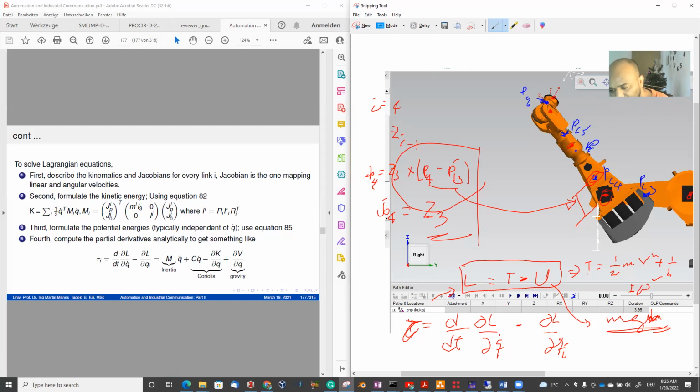If you don't know your exact point, you could use a jogging manipulator or a teach pendant on the robot, move the robot to this place, and by trial and error you will get your values. Or if you know the specific joint angles, say theta 1 is this, theta 2 is this, theta 3 is this, then you will get the result. The other way, if you have an inverse kinematics model, is to give the robot the end effector position, the Cartesian space or operational variable, and let the robot automatically compute the joint variables.